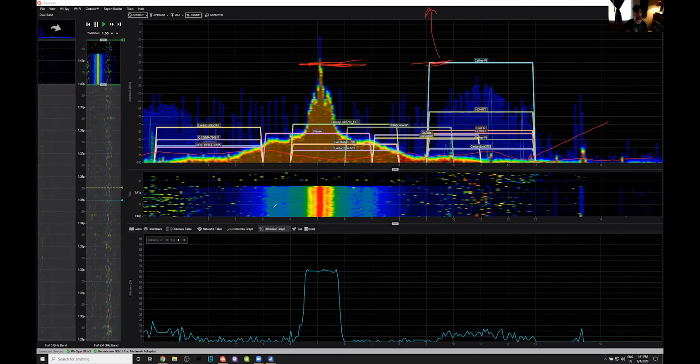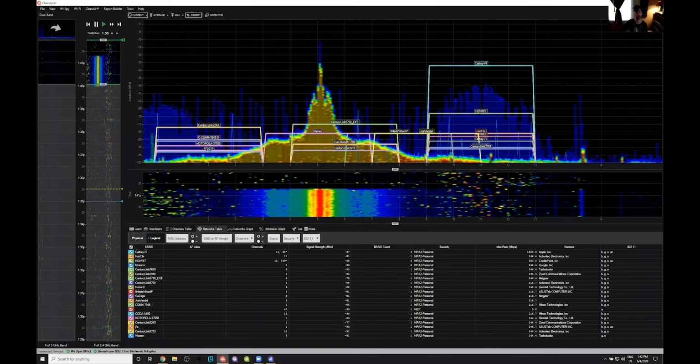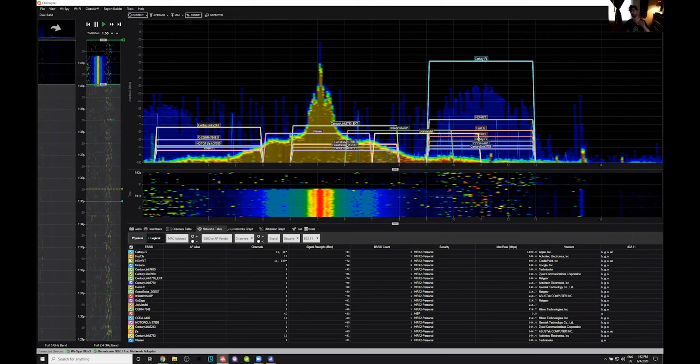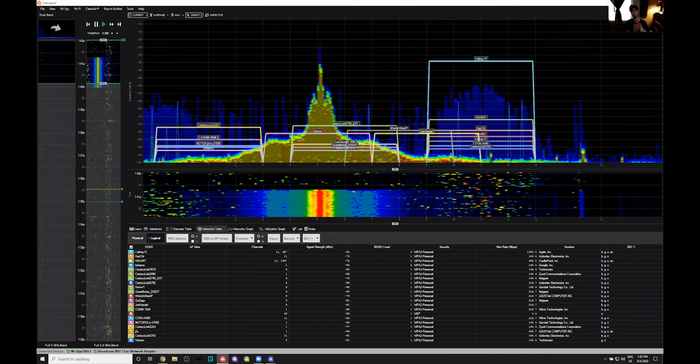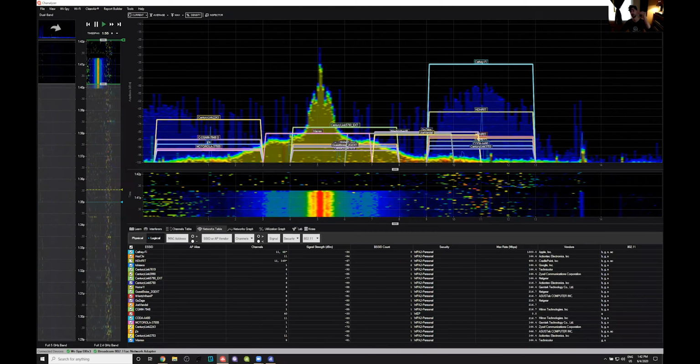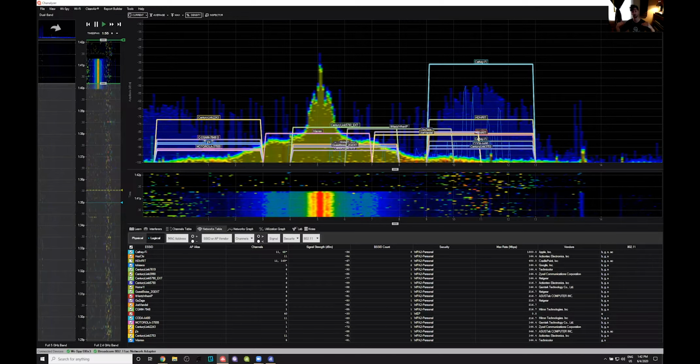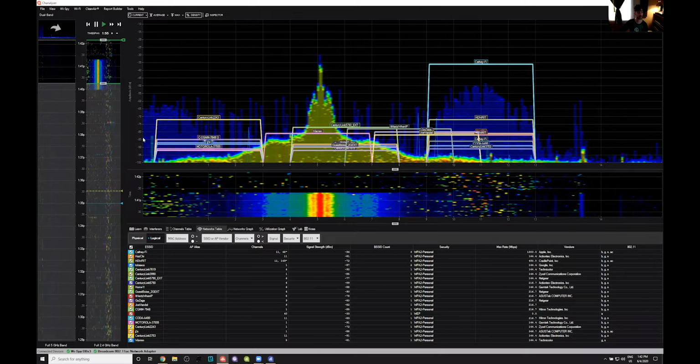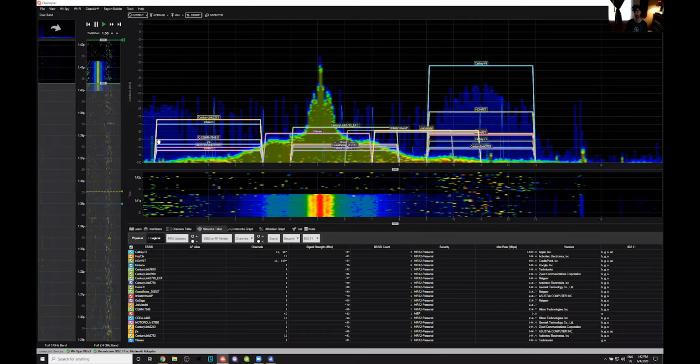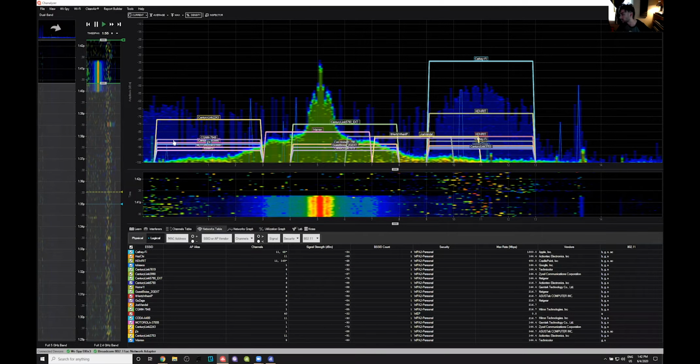So while I was talking about signal strength earlier in dBm and things like that, you know, negative 67 dBm, that's assuming you have a low noise floor. It might need to be higher if you're in a congested RF environment where that noise floor is elevated. If your noise floor is hovering at like negative 85, you actually need more than negative 67 dBm to have a good, reliable conversation. So that's a good point.